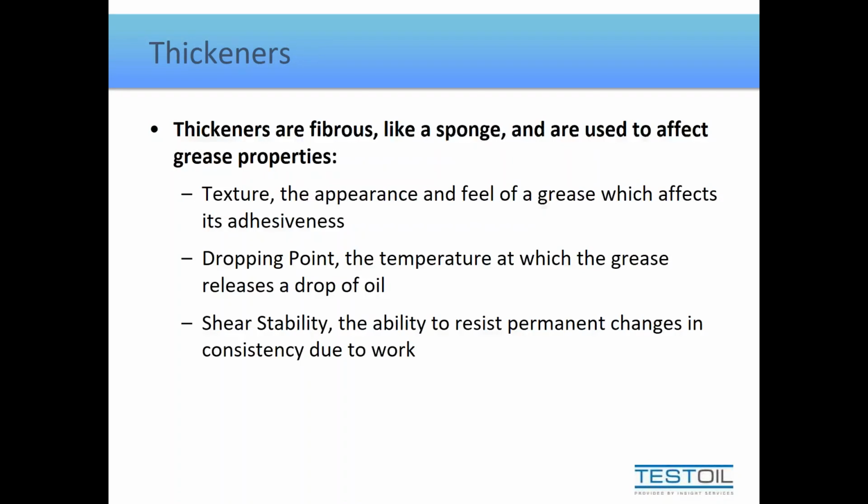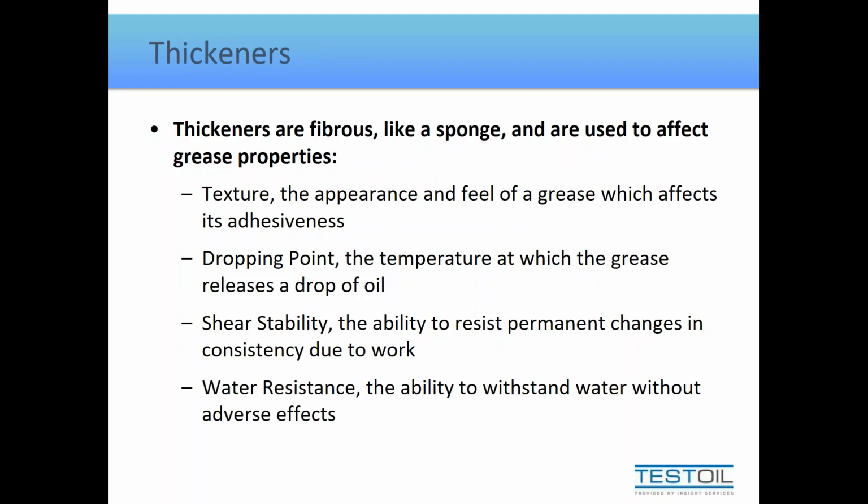We'll also deal with a bit of the shear stability, how well the grease will stand up to mechanical work, if its consistency will change or if it will remain close to new grease values. We have water resistance as well in some of our greases.